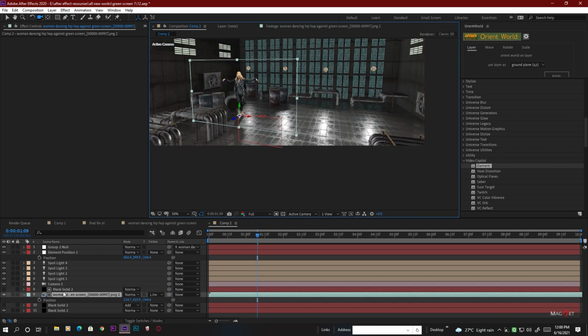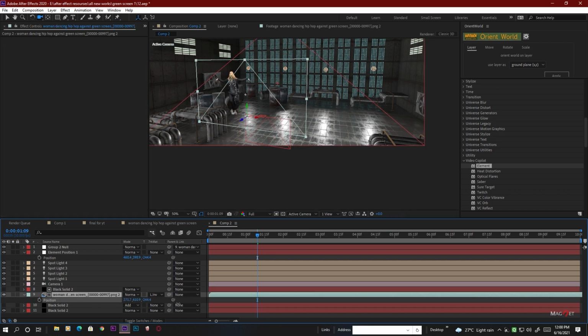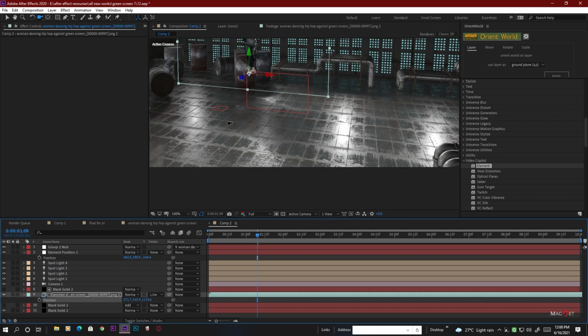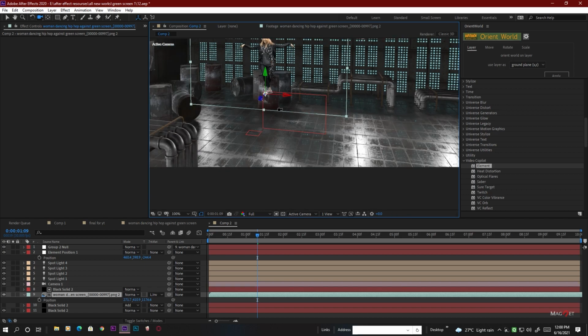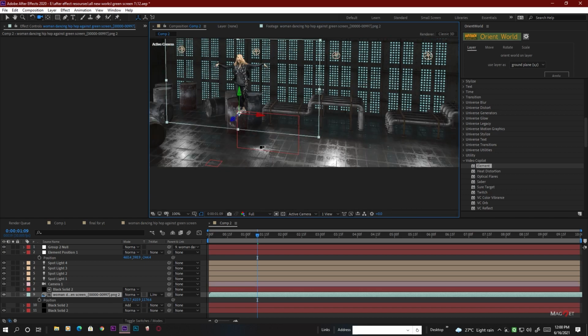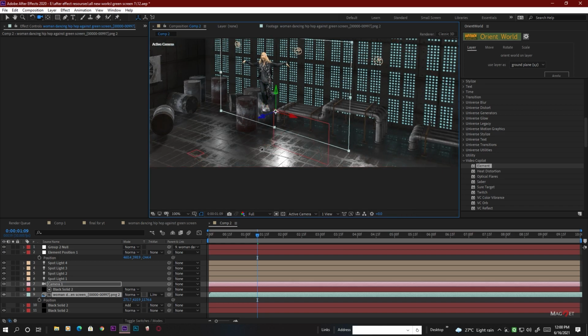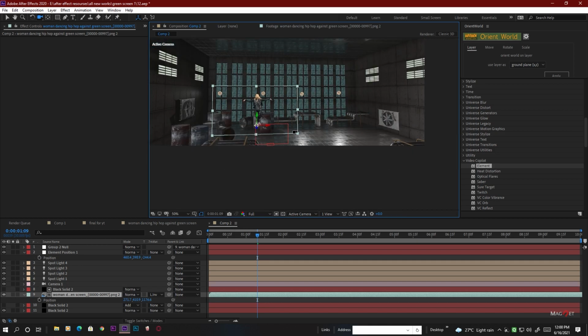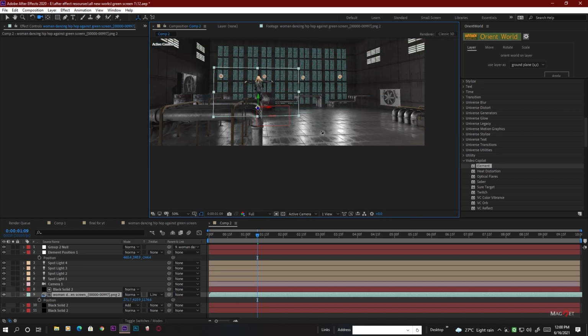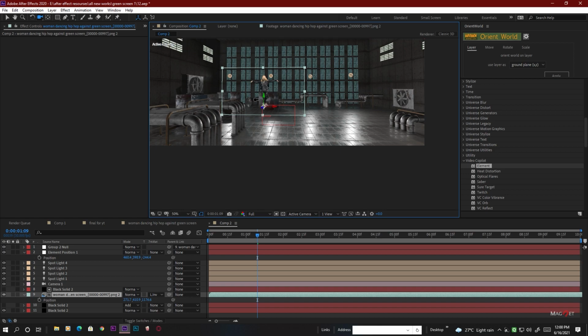But one thing, if you notice that once you change the position like this, if you place it behind those barrels, you can still get the same problem that the barrels are not in front of our green screen footage, and it does not look real. So you also need to link the world position pass with the green screen footage.